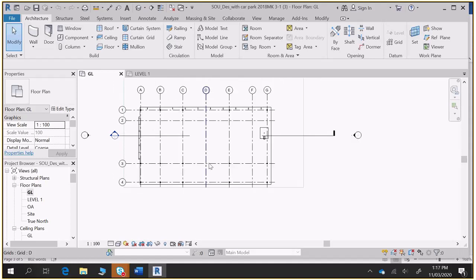They do become really annoying, the car parking. It's 4.2 meters? You've only got to get 2 car parks at 2.4 wide, 5.2 by 2.4, 4.8, which is a bit of an irritation, isn't it? But it's only 3 units. Yep, 3 units and 1 visitor car park. The visitor car park doesn't have to be under the main area. So there is a lot of space to play with, but you've got columns and things like that.